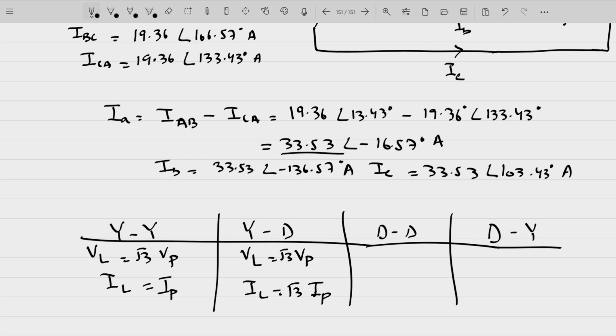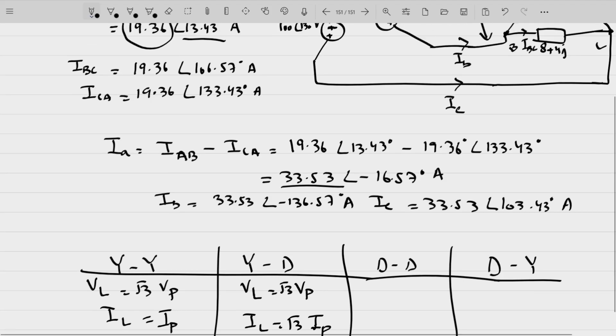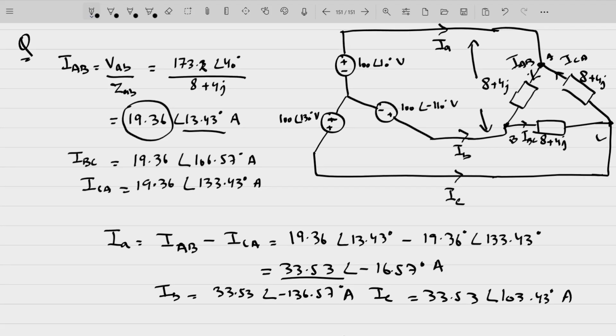Fine. So in a particular case, you might need more voltage but lesser current, so you can opt for star-star. But in some other case, you might need more voltage as well as more current, so you'll opt for star-delta. Delta-star we have to study, but once we study that, we can say for what amount of current and voltage, what sort of connection is better utilized. All these cases are only for balanced circuits.